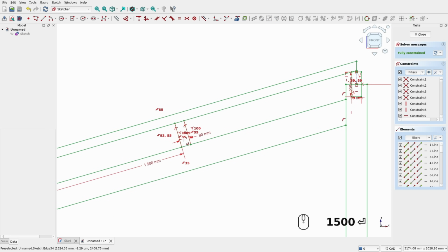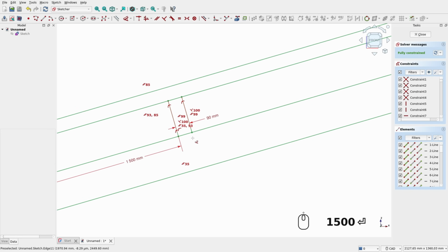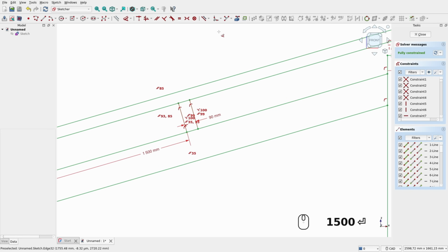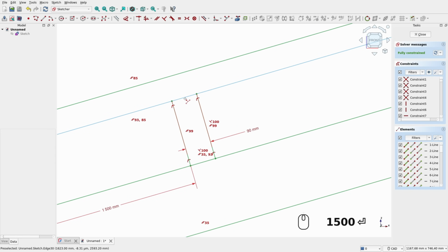Same deal as the post joints. You gotta break up those long lines to make the short ones for the section. Use the split edge tool to create 4 split points. Don't stress if the sketch turns orange. We'll fix it. Just keep moving those points.